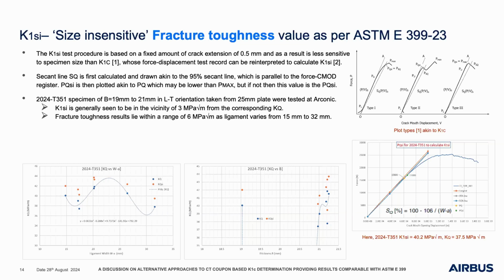Bob chose to change the preferred ratio, where there is a constraint between width and thickness within the E399. And there's certain conditions by which you can override it, but you can't override it beyond a certain point. Regardless, Bob decided that we should probably make specimen that were longer than allowed by E399. And guess what? The results we found was that it didn't really make a difference to the answer for aluminium 2024.